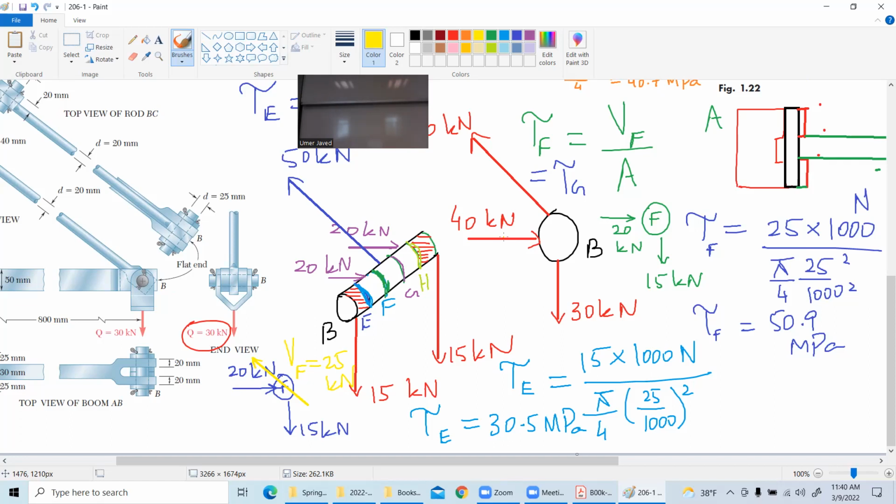It does make sense, because you can see that the hole is so big and the portion has become so thin, on both sides, very little. If it has to break, it might end up breaking here. So my intention is, why don't I find the stress right at this portion and at this portion, on both sides?